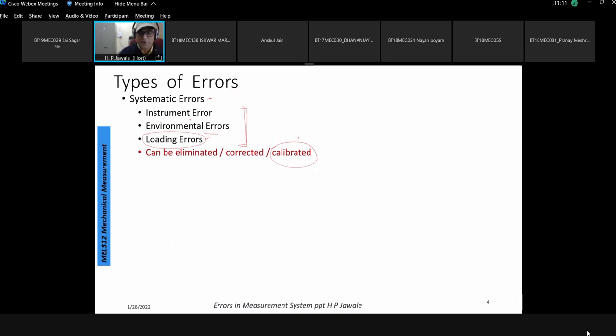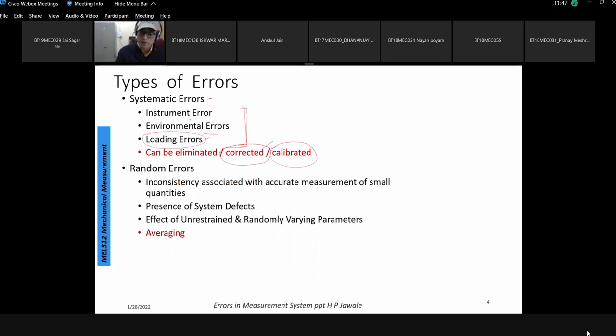Once it is quantified, we can think, for each measurement, suppose my input is 10 and it is showing 10.01. If my input is 20, it is showing 20.2. Then we know that this 0.1, 0.2 is nothing but the error, so we can directly subtract that. That is what correction is. If we know the response given by the instrument differs by a fixed quantity for a given input, we subtract or add that, and we can have corrections on the instrument.